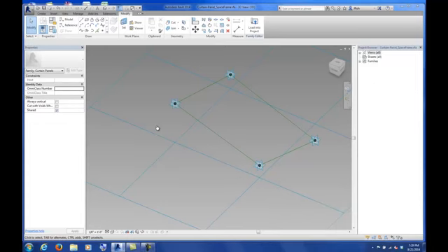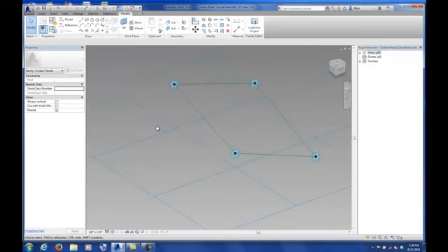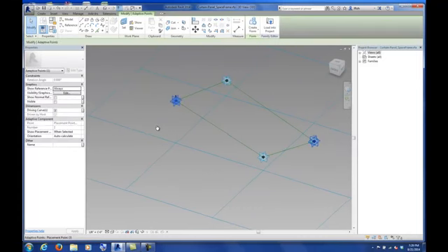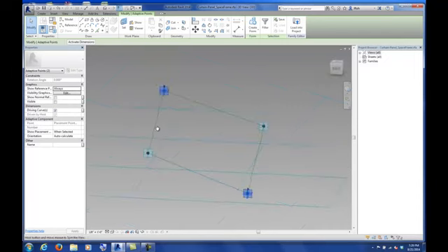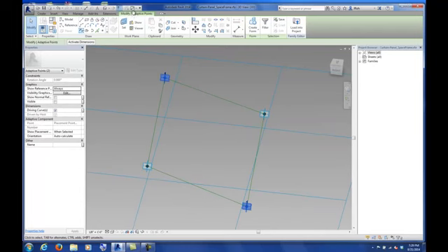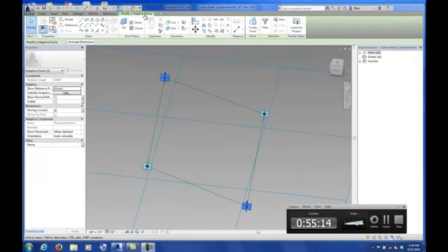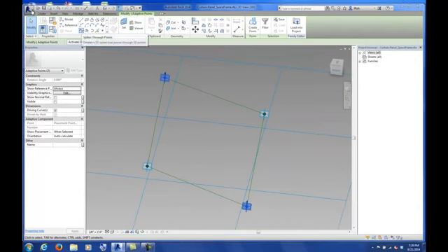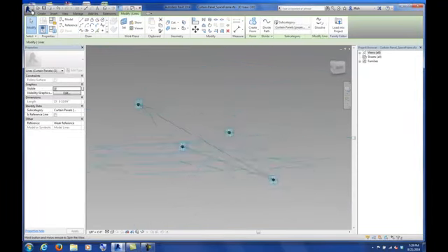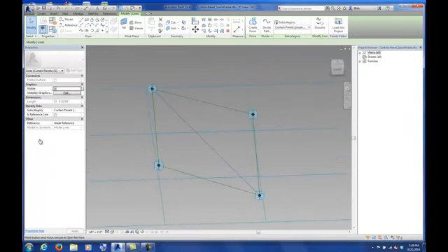Okay. All right, so what we're going to do here is I'm going to do a little bit of a setup so that we can make this space frame happen. I'm going to select the corner points, and it doesn't matter which corner you do, kind of the corner points across from one another. And I'm going to use the spline through points command and make that line connect from one corner to the other. I'm also going to select that line that we just made, and where it says is reference line, I'm going to click on it.